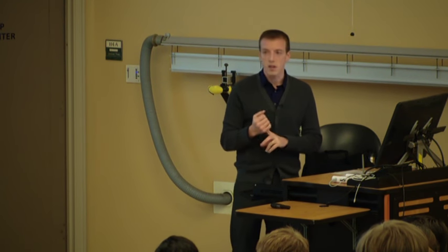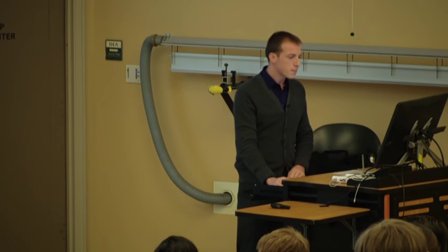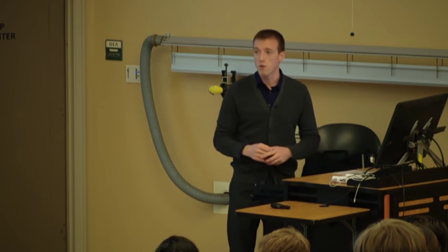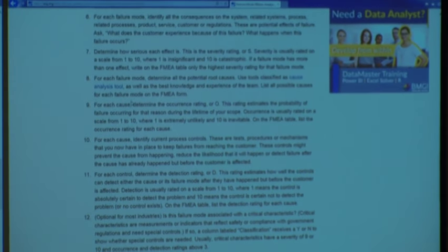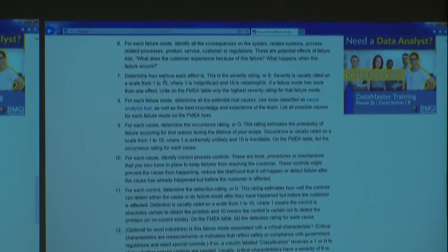So for each of those, you're gonna look at ways that failure can happen. Those are your failure modes. So mode is just a way, right? And then you look at the severity of each effect, how serious is it? So 1 to 10 scale is pretty normal.